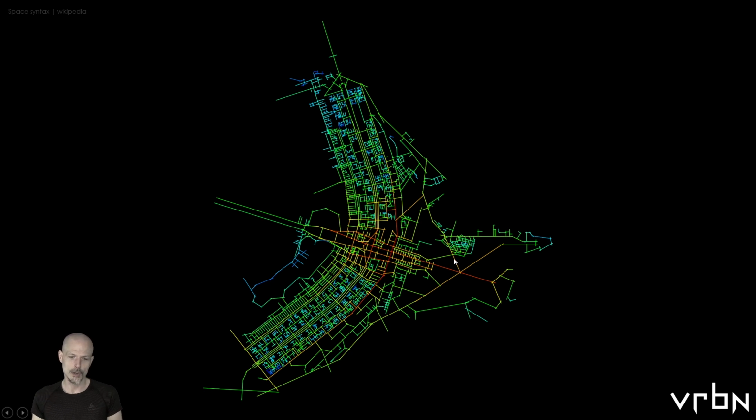And you see that longer streets that are straight become much, much more important for navigation. And the funny thing is, if you match, let's say, the color values to actual street widths in reality, they actually correlate pretty much perfectly. That would mean red streets here are very wide, have a lot of lanes, and blue ones here maybe just have 2 lanes, or potentially even 1. So that's something that is very, very interesting, and I think has to be considered when creating realistic cities, especially procedurally.